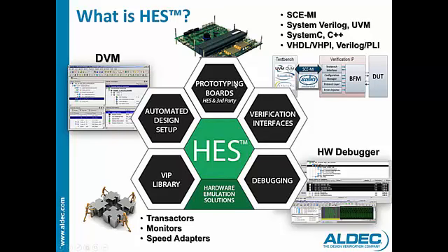SCE-MI is supported, which is the Accellera standard, and with SCE-MI it's possible to support SystemVerilog, UVM, SystemC, C++, and at the bit level we support the VHPI and PLI interfaces.